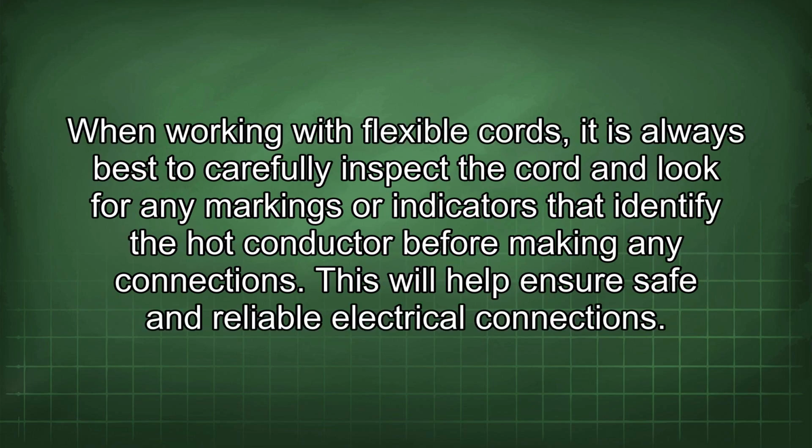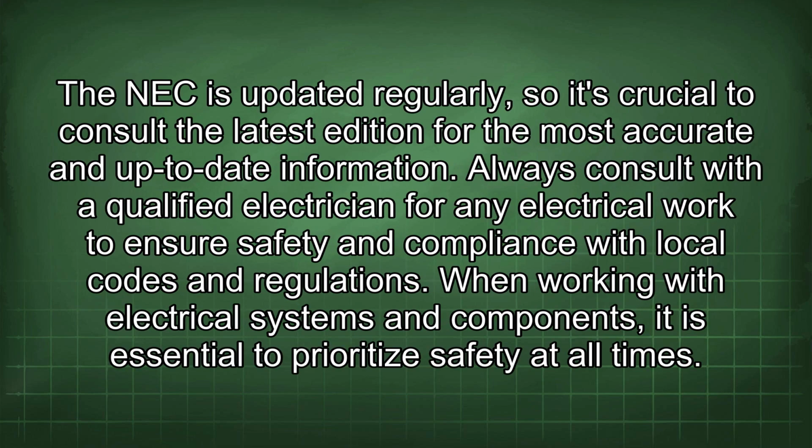When working with flexible cords, it is always best to carefully inspect the cord and look for any markings or indicators that identify a hot conductor before making any connections. This will help ensure safe and reliable electrical connections. The NEC is updated regularly, so it's crucial to consult the latest edition for the most accurate and up-to-date information. Always consult with a qualified electrician for any electrical work to ensure safety and compliance with local codes and regulations.